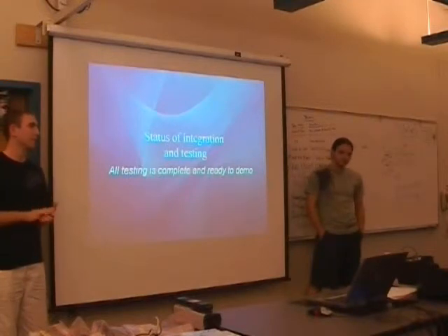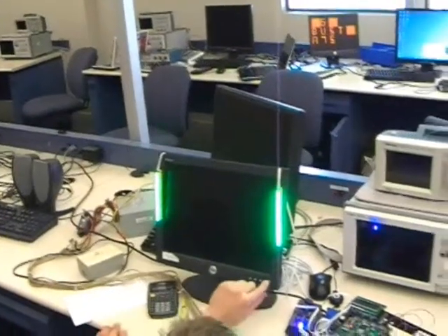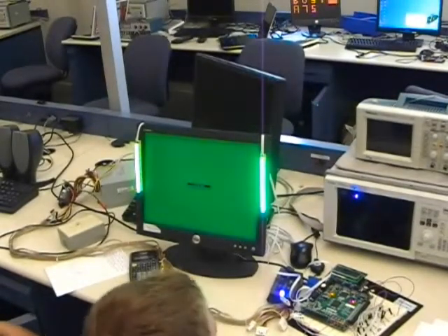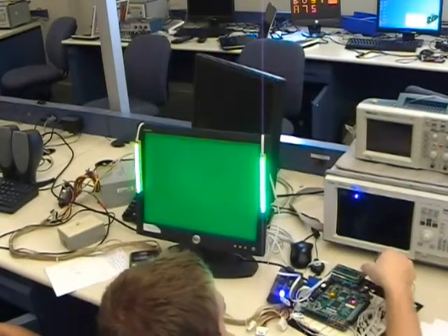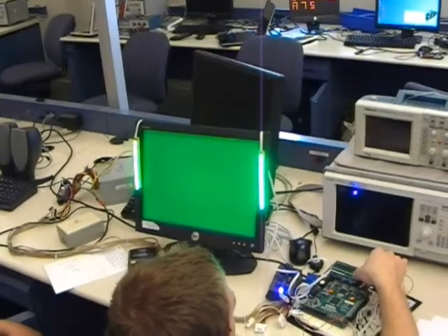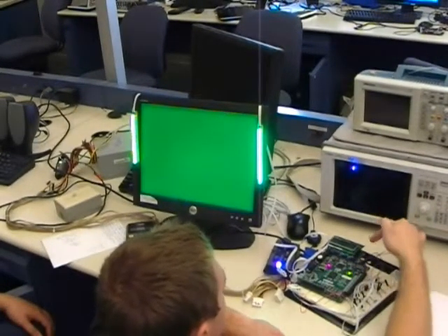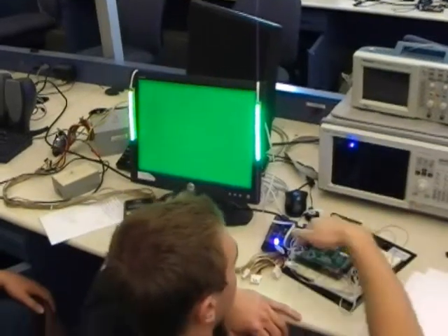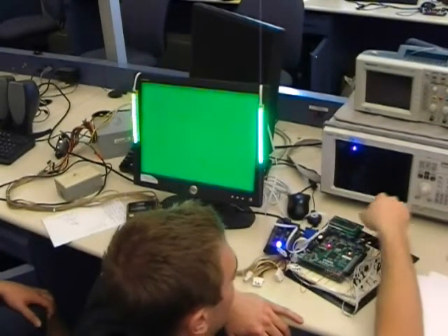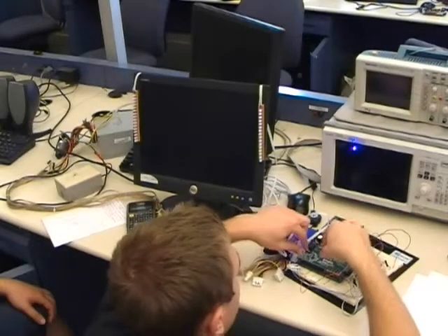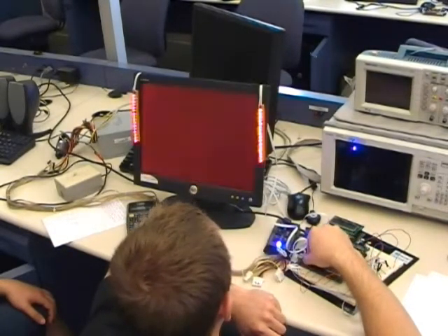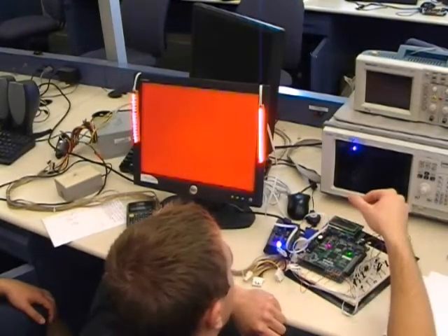We're kind of disappointed because the VGA only... I'm just going to start with this: the screen should just mirror whatever the LED is, so that's the VGA green. And then there's one switch that controls the master, so if you set this switch, that means you're in set mode. These 3 switches correspond to the individual colors if you want to set them via the switches, so you get 8-bit color. This is all at 0, so if you start increasing it, the red will start going up, to the brightest one. So that would be the red.